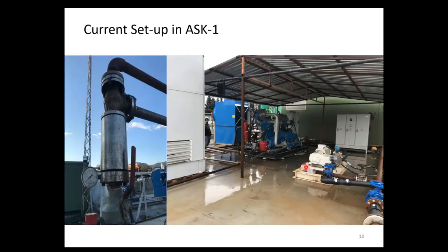This is the physical equipment: our fresh water pump, our compressor, our cooler. There is some other heat exchanger here, as you see, for the intermediate section of the compressor. I want to mention this compressor a little bit, since we re-inject all this NCG as it is coming from the well. There is a certain little amount of H2S, there is some CO2, there are some other minor gases.